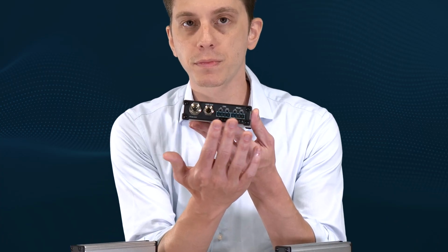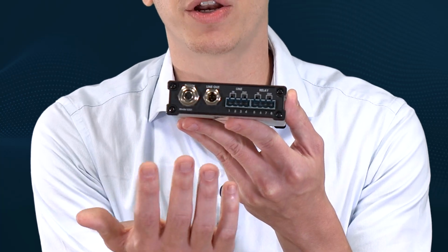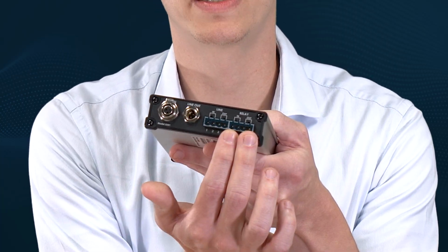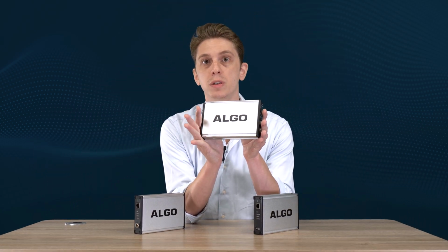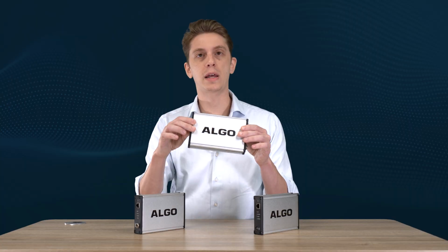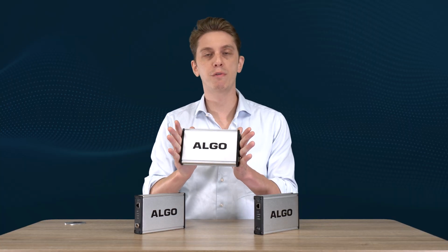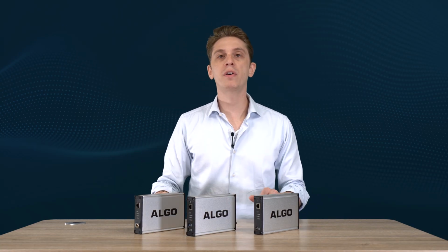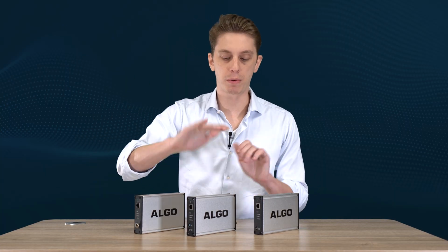Other than that, you have your audio outputs here. Most commonly, you're going to be using a terminal block line output. That's a 600 ohm configurable, I should say, but traditionally 600 ohms line level output, right? Whether impedance is configurable, it's a line level output. So this is going to connect into your standard amplifier, and you're looking into a page port, a line level port, or something like this on the amplifier, right?